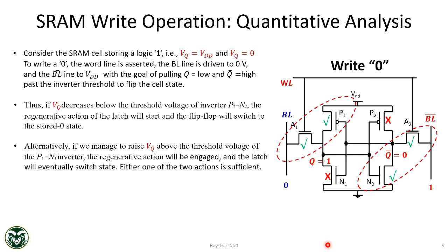So look, a couple of things here. There is no need for bitline discharge here. All you need to do is discharge this node. This node capacitance is in femtofarad, not picofarad, so it is a very small capacitance at Q equal to 1. That capacitance discharge takes orders of magnitude less time, and that's why write is faster. Read is slower because read requires discharge of bit lines. Okay?